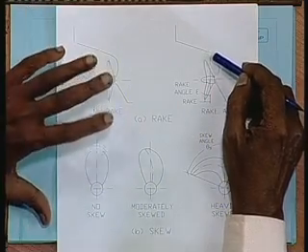We know that propeller works in a velocity field which is varying, and therefore it is possible that propeller may transmit pulsating pressure forces onto the ship hull, which may cause vibration in this overhang portion of the hull, that is the stern, which may be transmitted to accommodation and other areas.